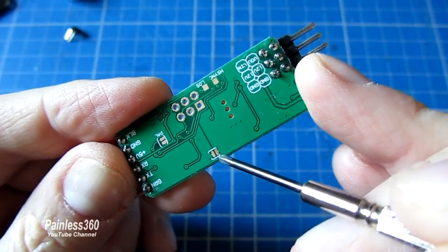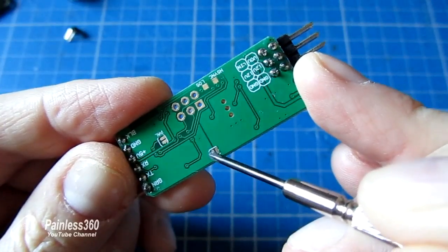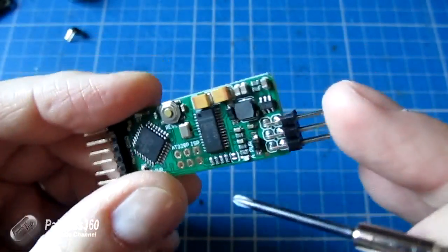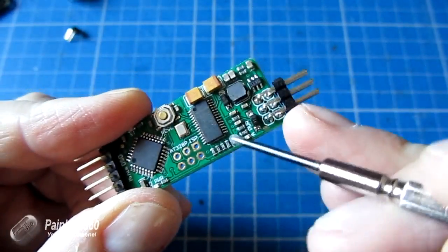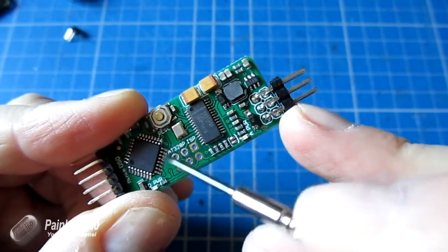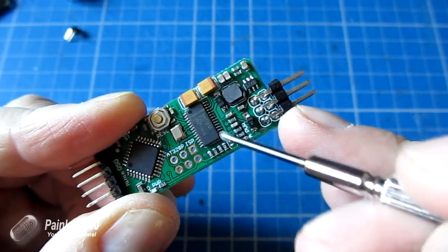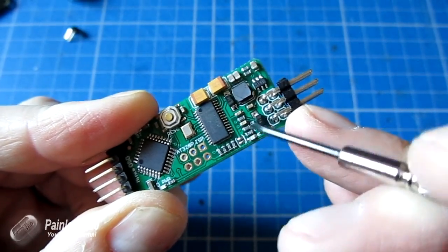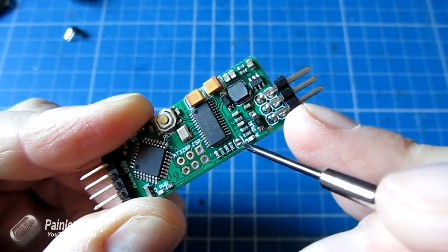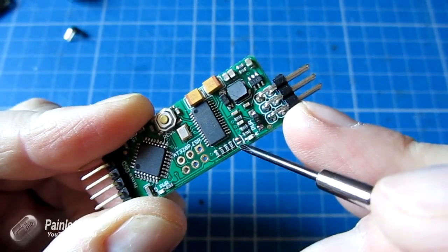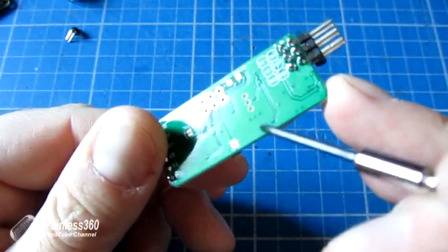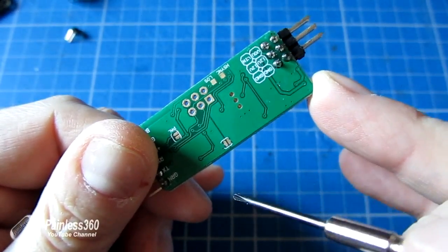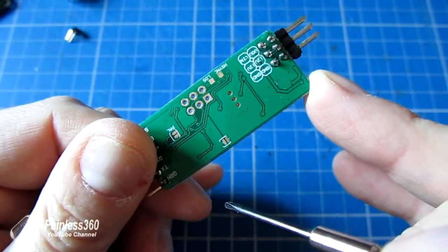And you can see they're made to bridge this ground plane with this ground plane on the back, and on the front the way it works is this connects this 5-volt system to this 5-volt system up here as well. Now we'll talk about this later, so don't worry about it for now, but just check that your board has a blob of solder that connects these two pieces on the front and a blob of solder that connects these two contacts on the back before we plug in our FTDI.